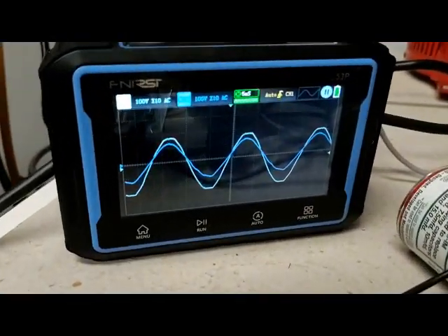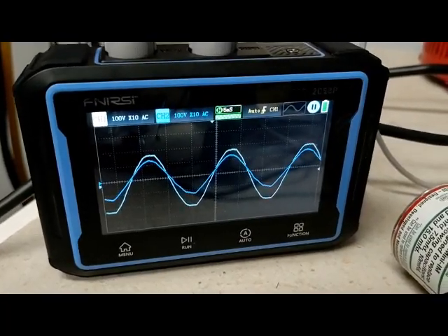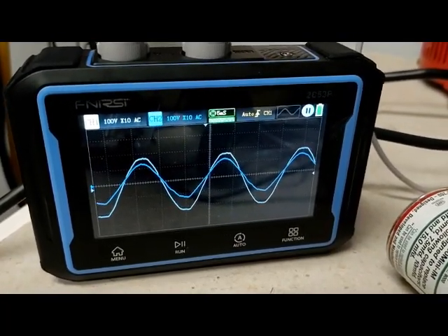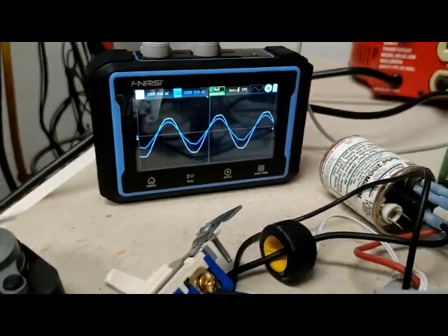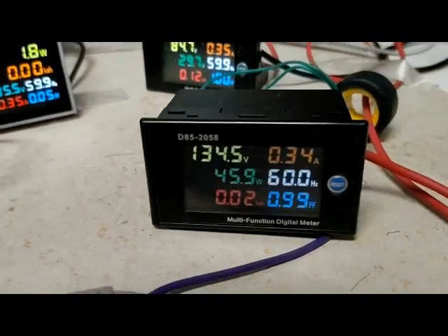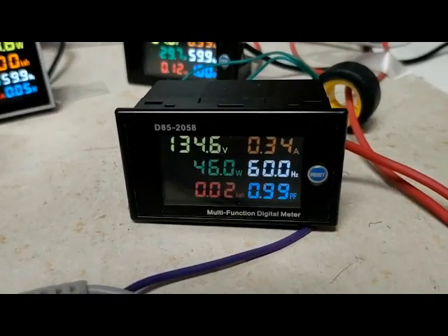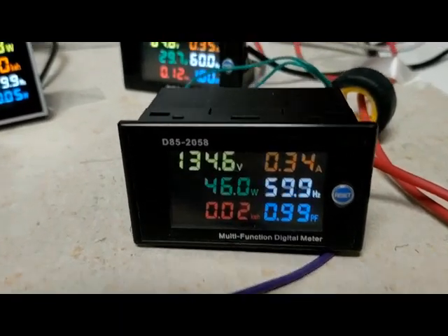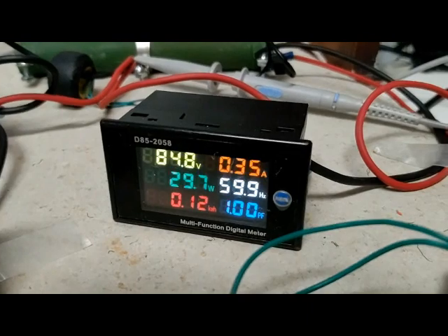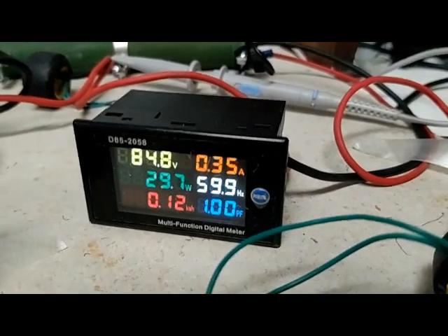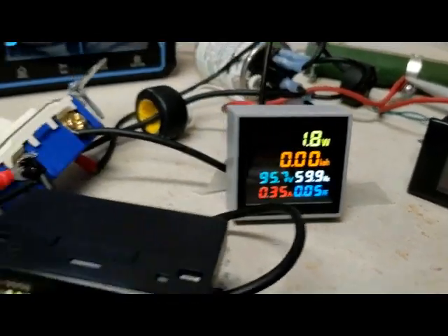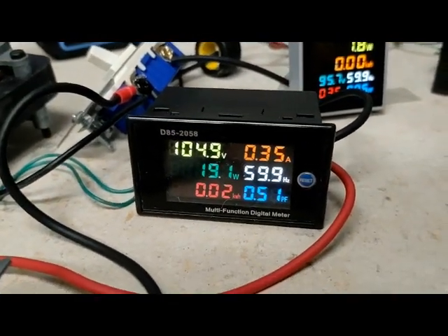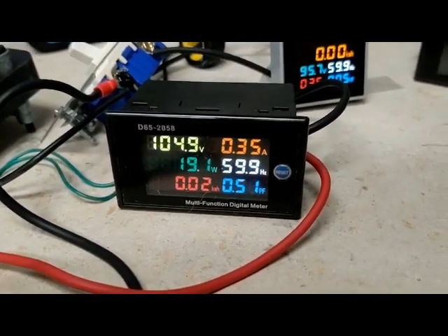So then the inductive reactance and the capacitive reactance offset each other, and we have a resonant circuit. And now the power factor for the overall circuit is almost 1. My resonance is not exact. You see the power factor through the resistor is still 1. Power factor through the capacitor is still terrible. And the power factor through the motor is still about half.